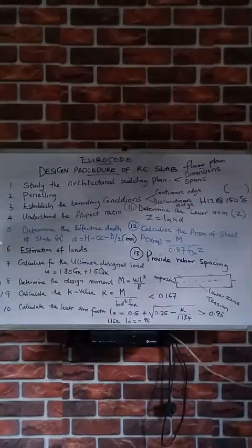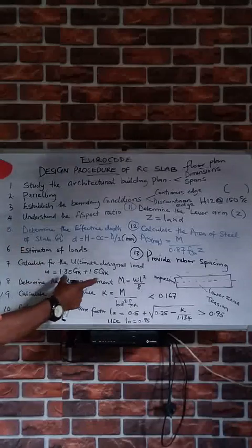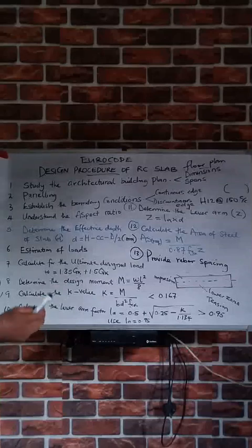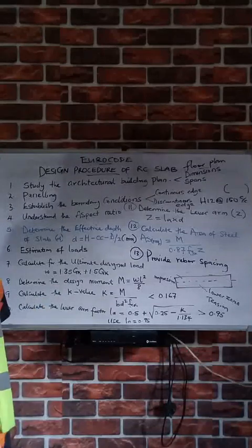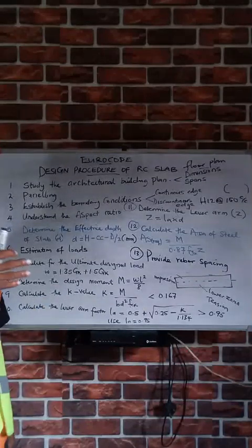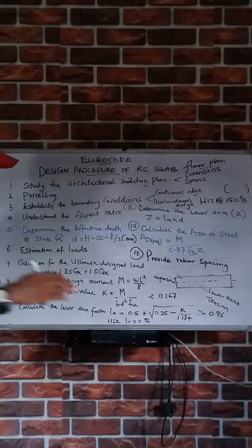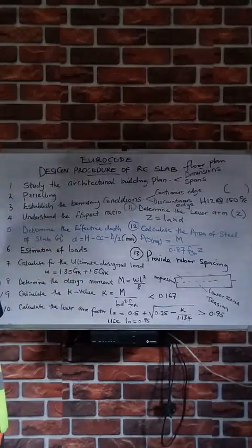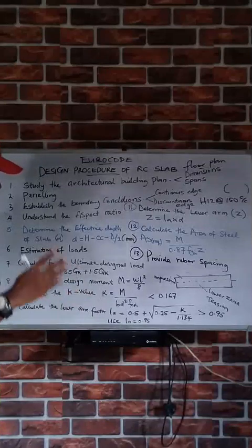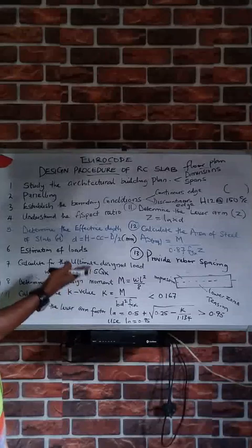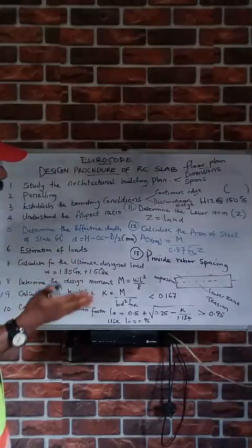Now understand that this is a factored load that I told you before. Okay, and in this case we can consider it as unfavorable. All right, we have some cases where we consider the permanent and the variable actions as favorable and unfavorable cases. Okay, but this provision is for the favorable case. Okay, and it's a factored load, so we consider this for our ultimate design load.